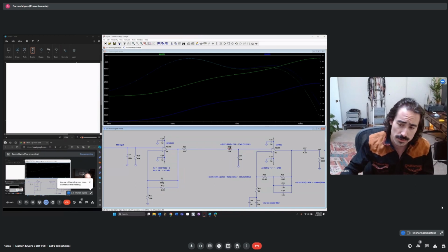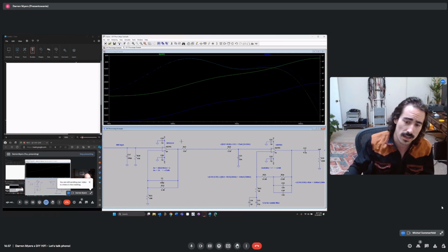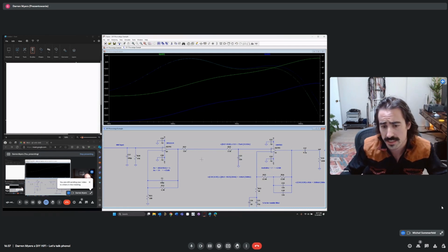And so the actual resistance creates noise by definition. And so we want to make sure that we get the signal up at a higher level where the noise of this resistance isn't dominant anymore. So that's the first reason.